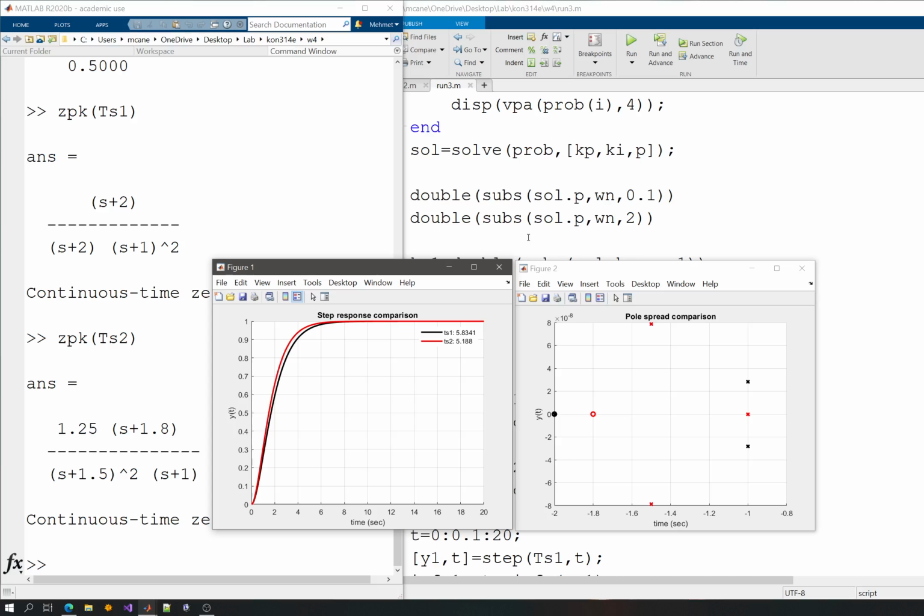It might be possible that we have a solution family that's infinite. It might be that we cannot even design a controller. These possibilities are there, but our approach will be to choose a pole pair that will be dominant, and the other ones will be placed hopefully far away from these dominant poles. I'm not talking about only the poles. The zeros should be held far away from these dominant pole pairs, because they will much more affect the system transient response here. So zeros are even more dangerous than you think.